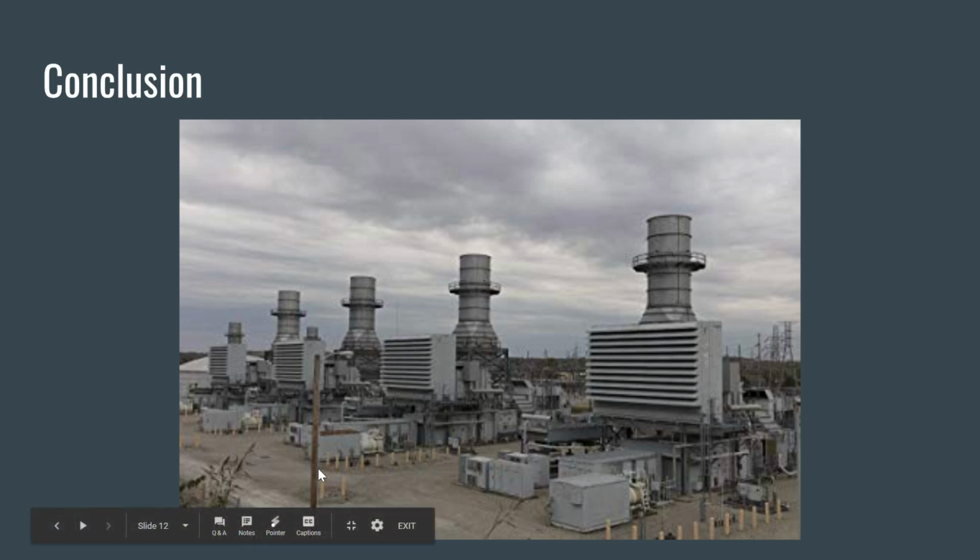In conclusion, we met two of the standards set by the NERC for stability. With this control system, we are able to ensure that the system is within our settled frequency with 32.78 seconds less than the time the system was allowed to be off frequency and still be within the highest level of standard compliance. We were also extremely accurate with our system after every disturbance, and because of this we are within the 5% error margin that the frequency is given.